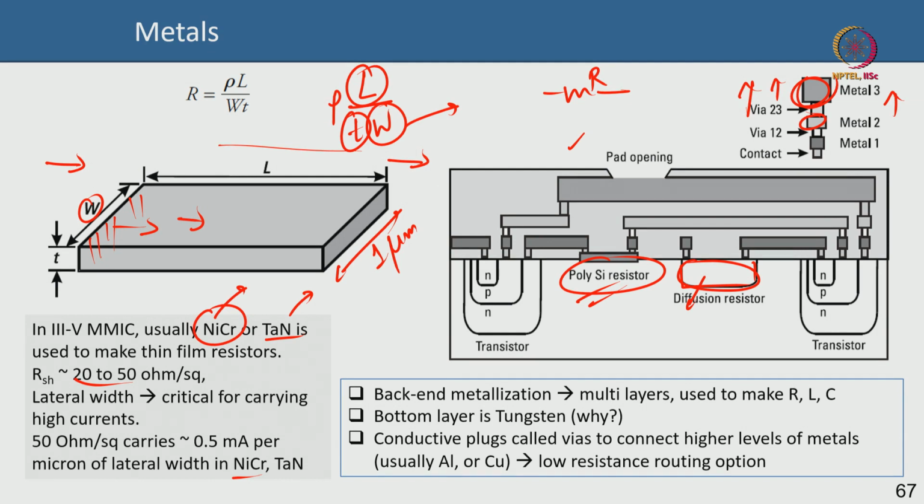So typically nickel chrome is used as a metal resistor, but in a CMOS process you can have a more elaborate back end of the line, BEOL, and you have a large number of interconnect vias and things like that. So you use these tungsten plugs, for instance, to integrate these different vias, and you need a low resistance metal such as copper or aluminum, so that your routing becomes easier. You don't want a highly resistive metal, because the more you go to the top, the more conductive your metal should be. You're carrying more current from multiple vias and multiple connect lines.